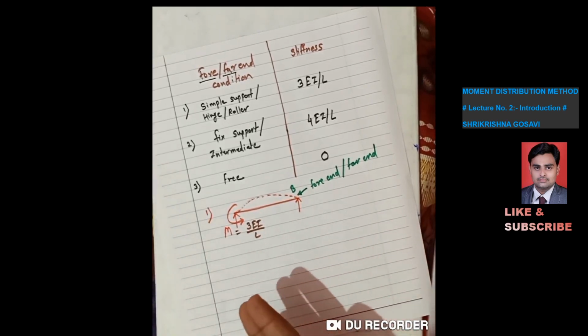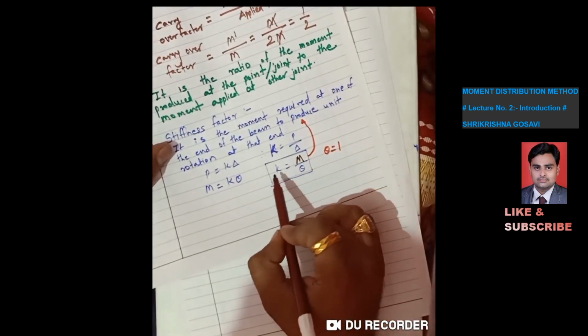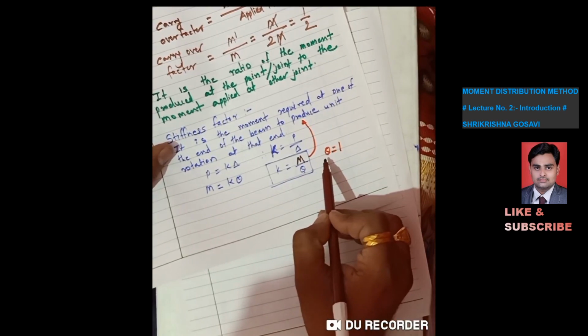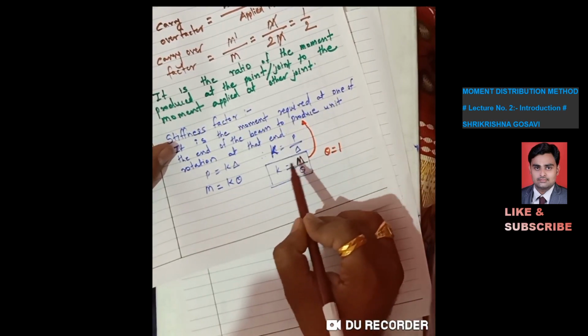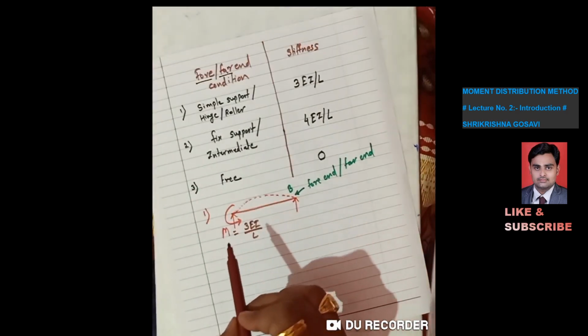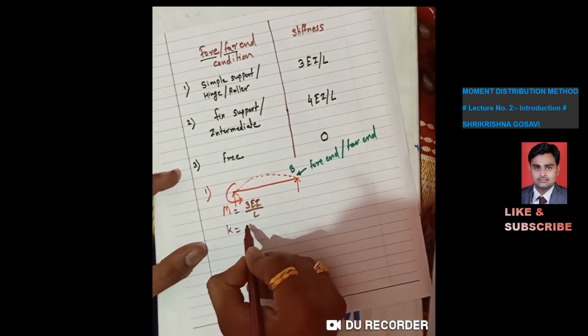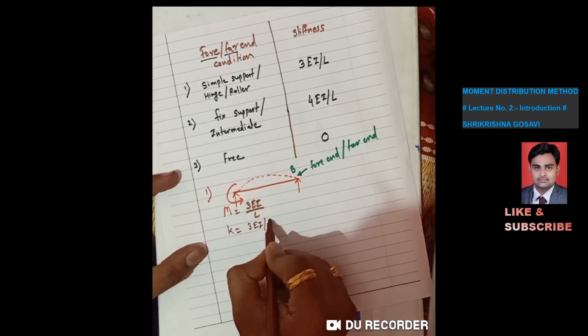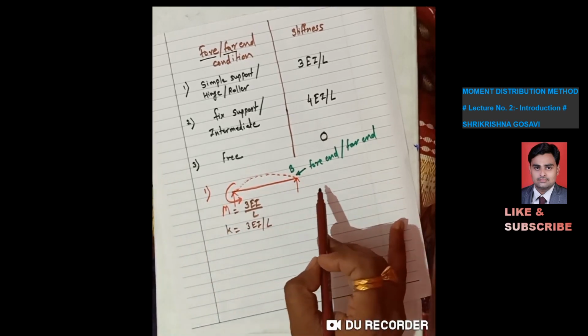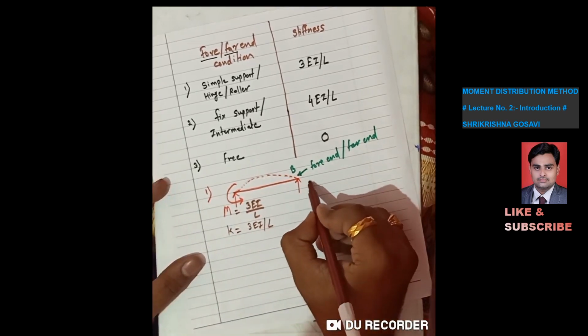The value of M and K is the same, as I told you over here, because we put theta equal to 1. Whatever may be the value of M, the same is the value of K. So M is nothing but K. I can write K is equal to 3EI by L if the far end is simply supported.